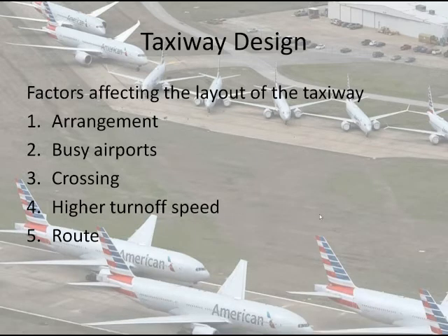Such taxiways are known as exit taxiways or turnoffs. For busy airports, where taxiing traffic is expected to move in both directions simultaneously, parallel one-way taxiways should be provided.